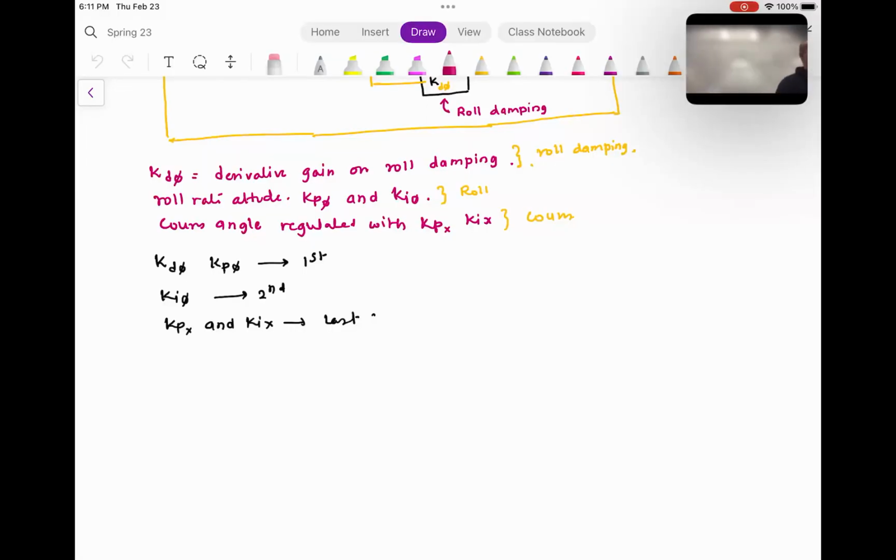So what we are going to do is, now we started talking about this successive loop closure, and let me reiterate, at the end of the day, the process for controlling any flying robot is the same. As a matter of fact, out of those 12 equations that we talked about, those are the fundamental equations for a flying body, no matter what the shape of the body is.